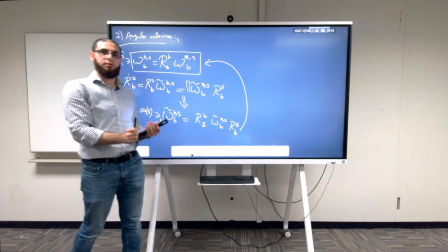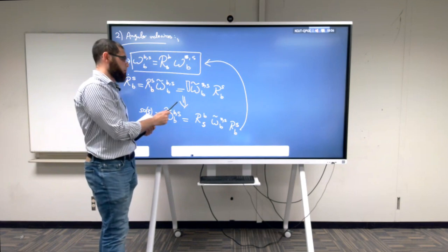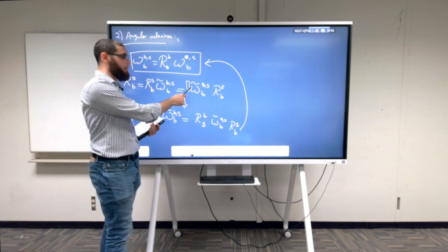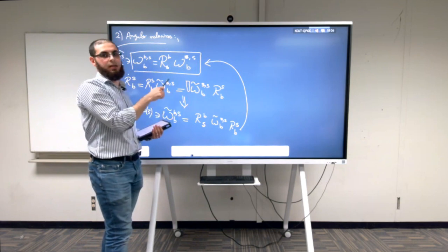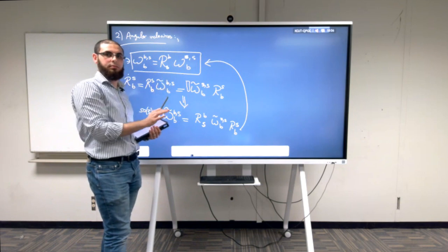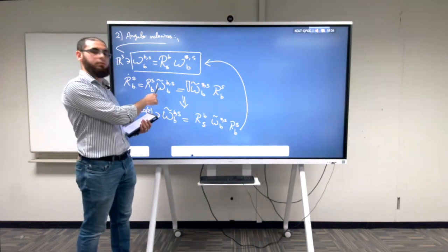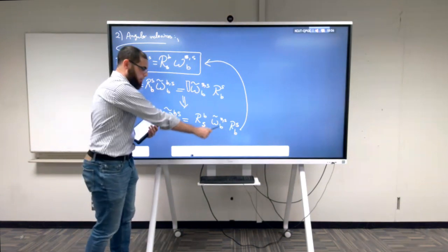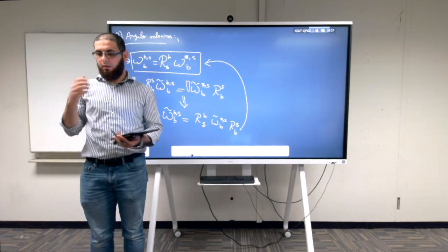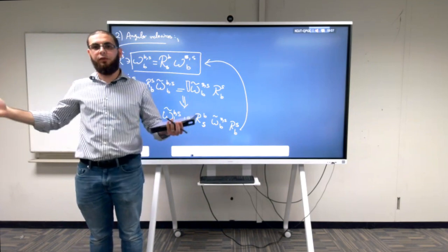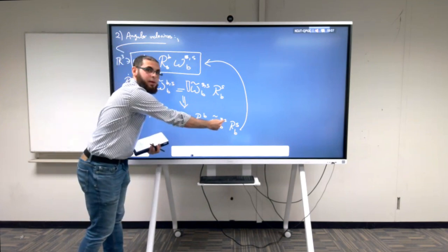I'm sorry, I don't get the question. The elements of that, like that's the 6 degrees of freedom, right? Now omega tilde B is a 3 by 3 matrix that's skew-symmetric, so it has 3 numbers in the end. Yes, those elements change from whatever we have here. So this 3 by 3 matrix is different from this 3 by 3 matrix. Absolutely, because they both represent the same thing from 2 different frames. They both represent the rotation of frame B with respect to frame S.